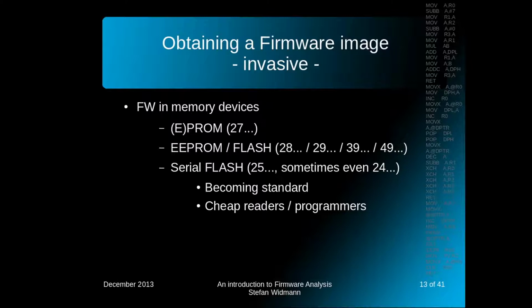But very nice to see is that serial flashes, those 8-pin devices, 25, sometimes 24, are more and more becoming a standard. They are easy to desolder, easy to resolder, and there are very cheap readers and programmers available. But please, even if some say we can do it in system without desoldering the chip, please don't do it. It can lead to very big problems.